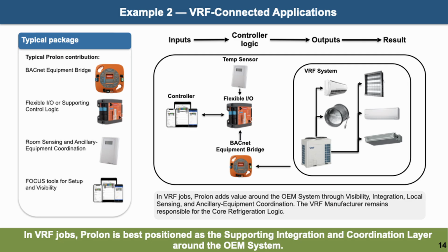This can be especially useful when the project requires visibility, local sensing, ventilation coordination, makeup air coordination, or integration with a broader BAS. The important message is that Prolon improves visibility, coordination, and support around the VRF application, while the VRF manufacturer remains responsible for the core refrigeration logic.